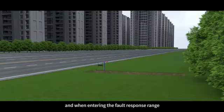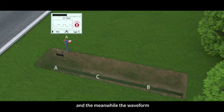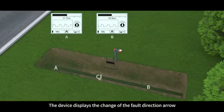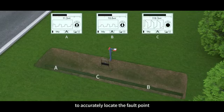When entering the fault response range, the voltage will rise, and meanwhile the waveform and the fault location arrow will gradually stabilize. This indicates the fault point has been approached. The device displays the change of the fault direction arrow to accurately locate the fault point.